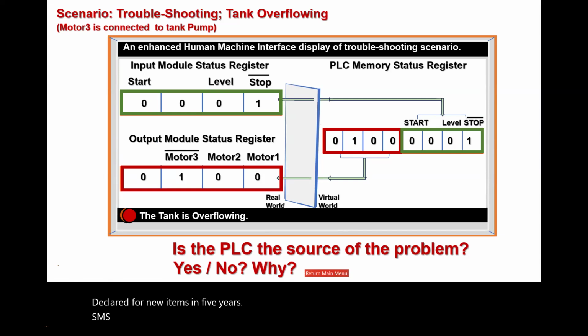And what's the signal being sent to the motor? A logic 1. So as far as the programmable controller is concerned, what's going on? Nothing. And it sent the information to do what with the pump? Turn it off. But what is happening? You're up to your waist now in water, by the way, because you haven't moved away from the control panel. Where should you be swimming to? You should be heading to where the pump is, because there's something electrically or physically wrong with that pump part of it. Everybody sort of see where we go with this?